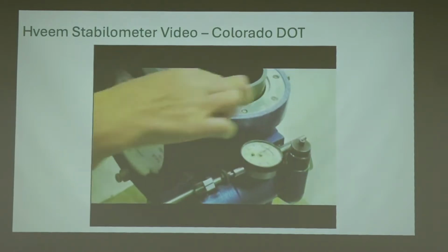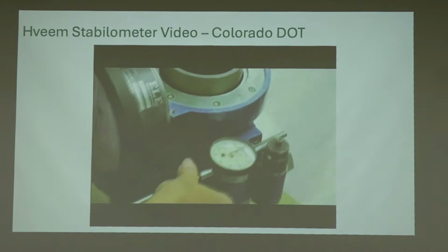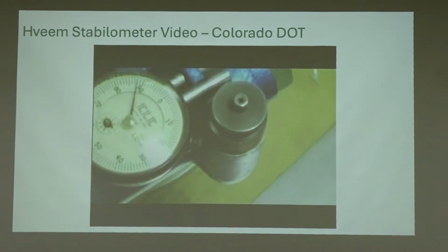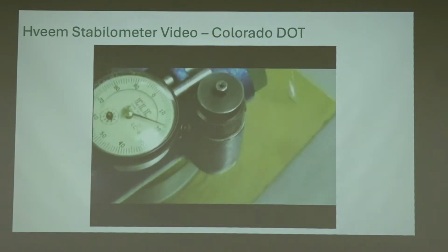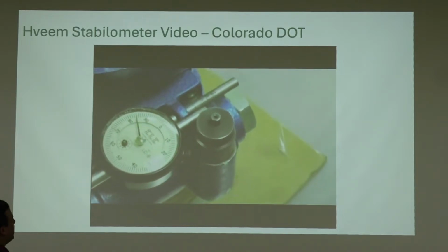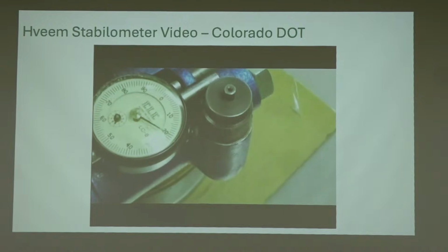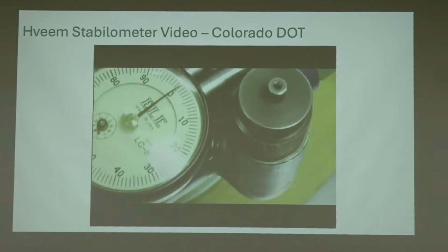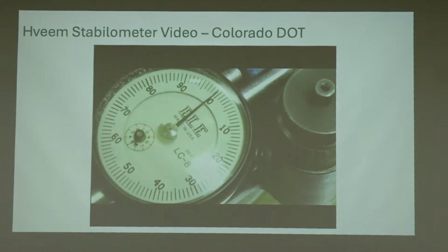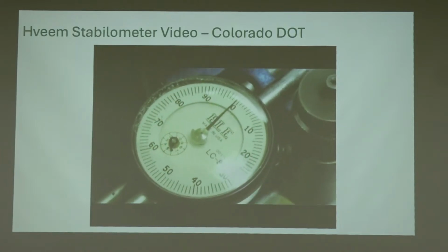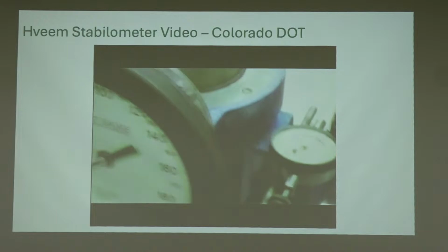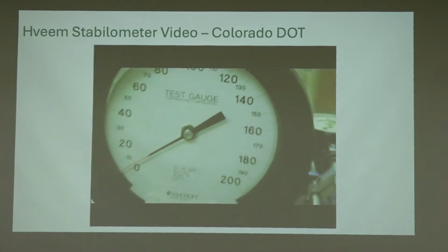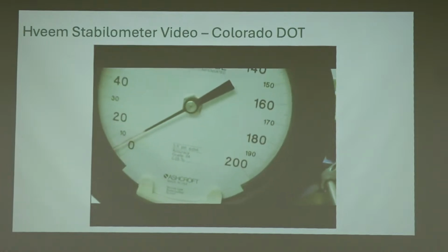Once you have both of those dials set, you're going to be turning the horizontal pressure handle out exactly 2 turns, watching the turns displacement dial. So this is all related to calibration. You should not worry about that much, the initial part. So if the needle is a little above the 5 psi, you're going to have to let air out. If it's below, you're going to have to let a little air in.